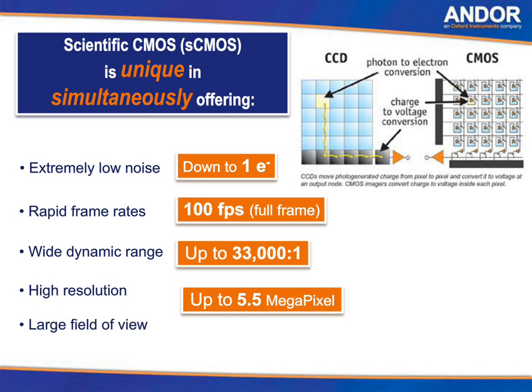All scientific CMOS brings is the effective linearity of response for the CCD-like qualities to a CMOS structure. So what we've developed is effectively a CCD performance in a CMOS structure. So that gives us all of the advantage of fast clocking and the large field of view, which we then want to maximize. So if we move to the next slide,